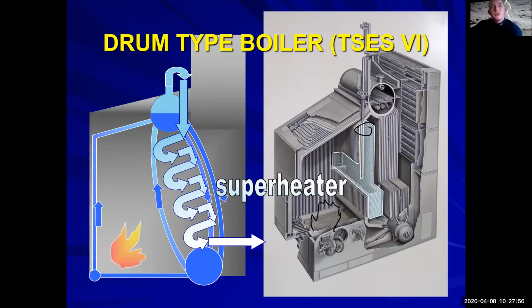It's the superheater tubes because they're smaller and they'll just melt or something. So they don't have any liquid in them. All right. So they're not necessarily being cooled, the tubing. It could take the heat, but not a direct source. Is it just steam in there? It's just steam in there. The superheater has only steam. There's actually a baffle here that keeps any water molecules from entering if they're getting dragged up through the steam.